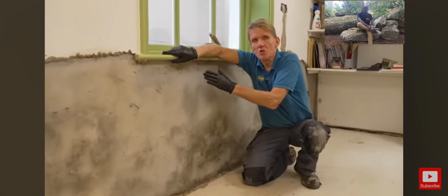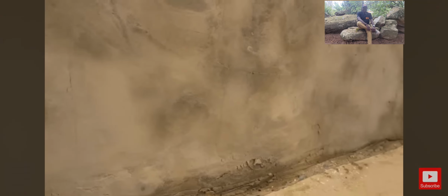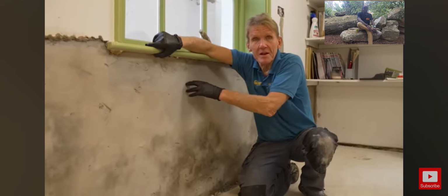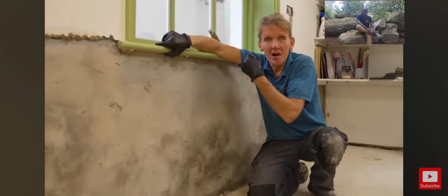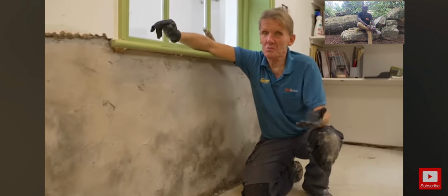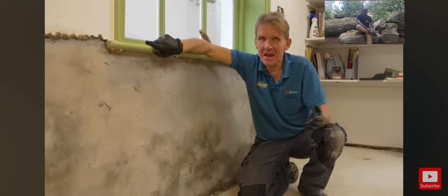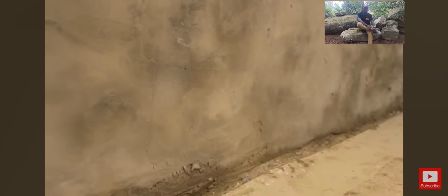Now, if you've got salts in the wall, which happily we didn't have in this situation, this TS Plus will also help keep the salts back. So once we've done the 2 coats, we're going to leave that to dry overnight, and then I'm going to apply Highline plaster, which is a renovation plaster. Again, it's got this breathability. I hate using that word all the time, but people understand it. It means that it allows the moisture in vapor form to escape through and not trap it.